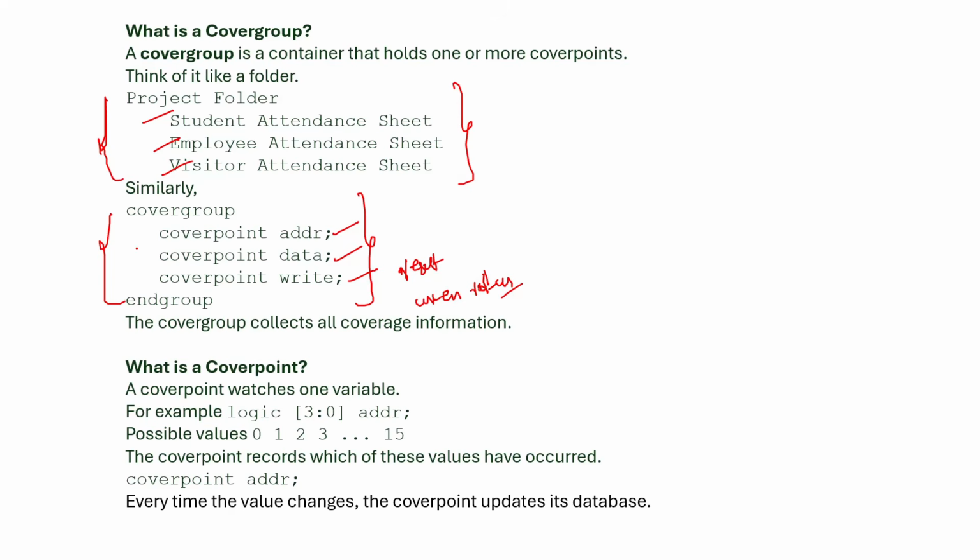And what is a cover point? A cover point is an integral expression or some variable you are representing that defines the behavior. What type of behavior we are getting, it will collect that coverage. Cover point is the values or expressions or integral values we are giving, and it will tell you the behavior.